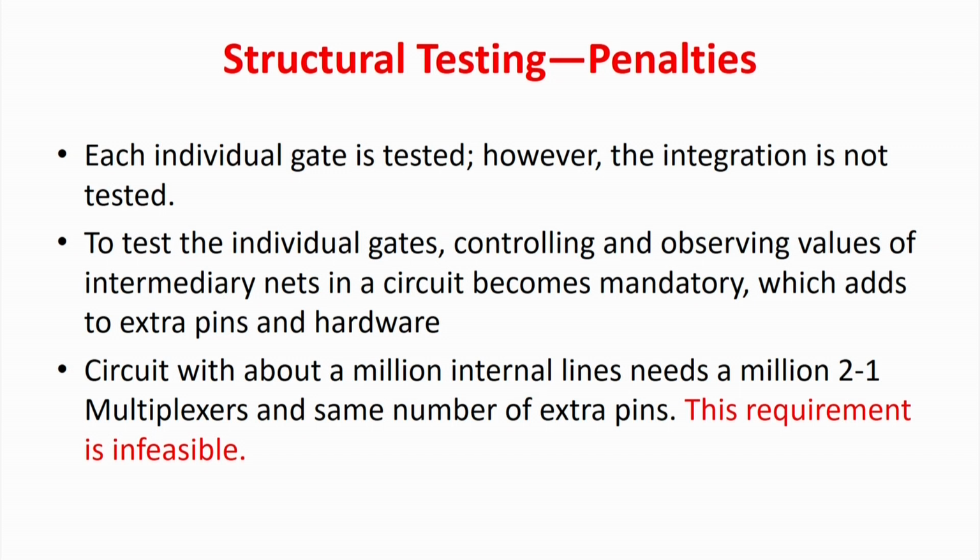So, one main issue is that, now let us look at the penalties of structural testing. Each individual gate is tested, however, the integration is not tested, but that is a minor issue, because already by handling large number of cases, people have found out that the compromise is not much. But to test individual gates, controlling and observing values of intermediary gates becomes mandatory, which leads to extra pin and hardware, that I will tell you.